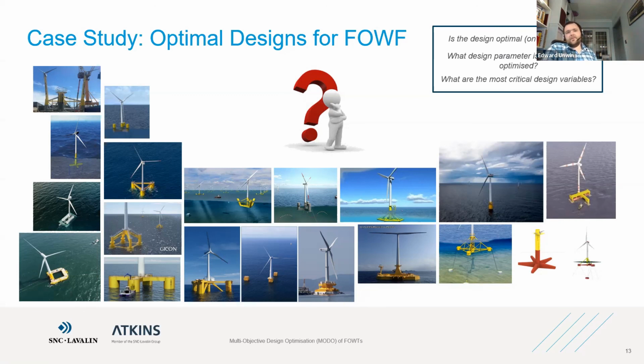But there's an argument that if it's only a moderate magnitude of motion, it might be that it never really leaves the tolerance for the alignment of wind direction to actually warrant activating the yaw motors, and it'll just generally follow the change in wind direction.